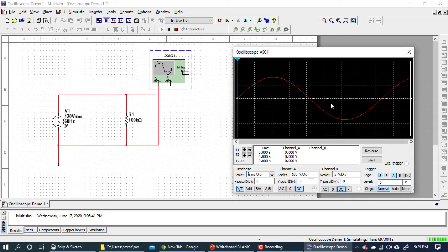Now, do you remember how to calculate, since this particular oscilloscope does not calculate frequency, and older oscilloscopes don't either, do you remember how to calculate the frequency if we know the period? So real easy formula. In other words, F, which is the frequency, equals 1 divided by the period. That's an easy one. So you just put in the amount of time that represents the period of the waveform in your calculator, and then you hit the 1 over X key. So it's the inverse.